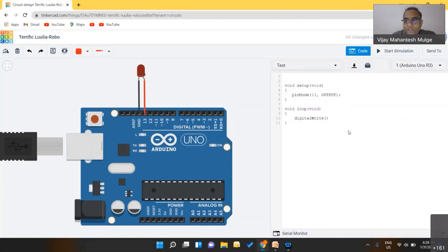So basically you can use it to write a value of 0 or 1 on any of the pins that are there on Arduino, written as D0 to D13. Which pin am I using? I'm using pin number 13 here. I will write a value called HIGH, which is nothing but a value of 1, whereas LOW is nothing but a value of 0. So I have taken the pin number, I have decided which pin I'm using, then I'm writing my logic here. Logic is what? I'm deciding what needs to be sent to the LED here.